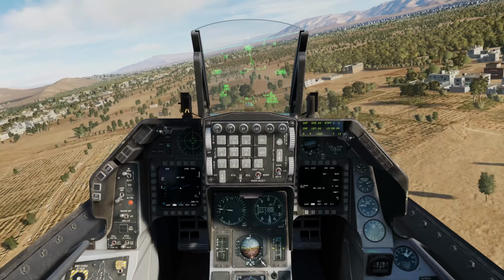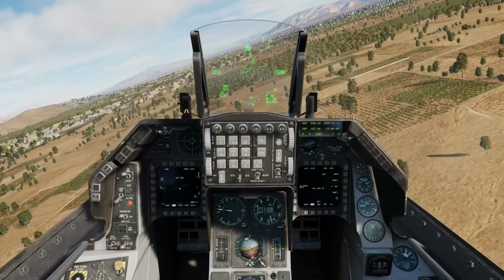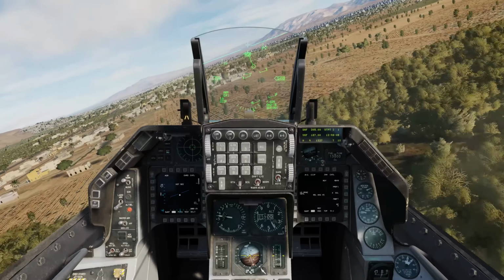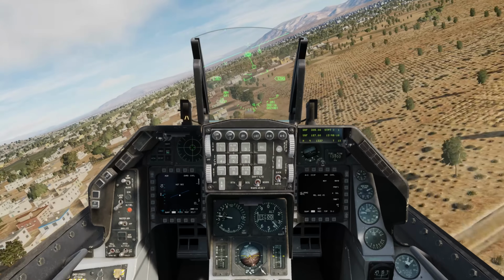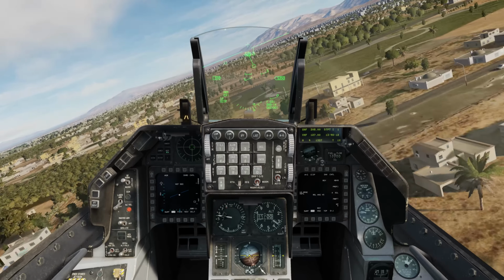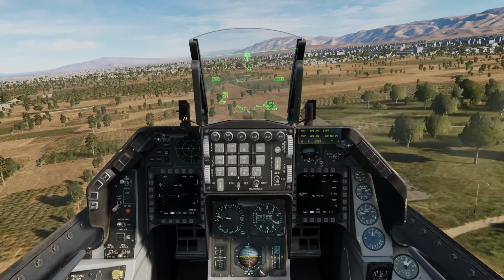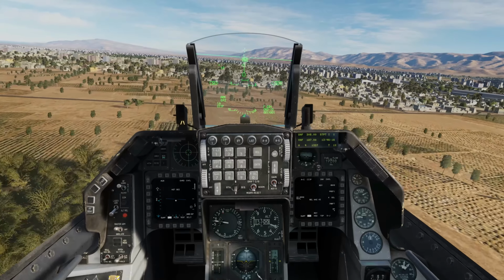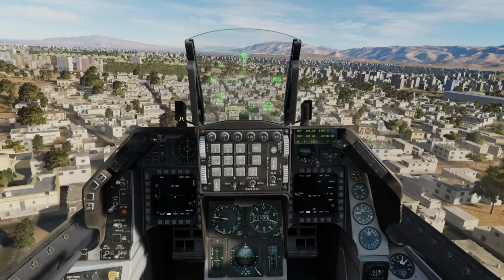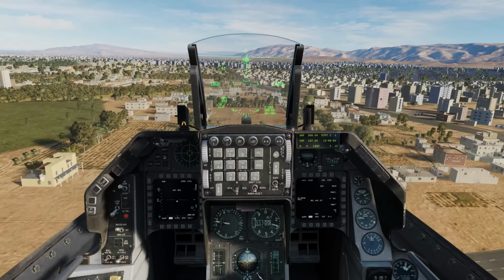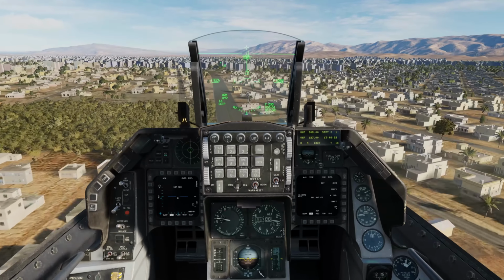Our next step for the Viper will include methods to check and update the location of steer points within the navigation system. This will include fix taking from the FIX DED page and altitude calibration from the A-CAL DED page. For this first video, we'll discuss fix taking.